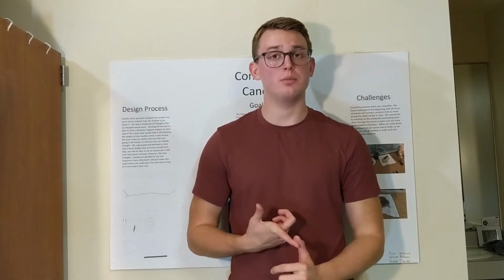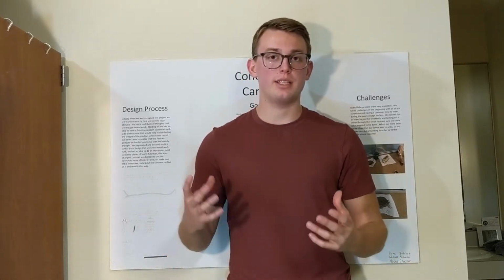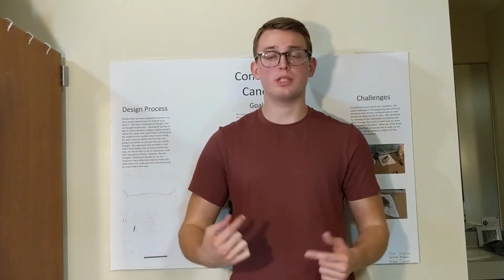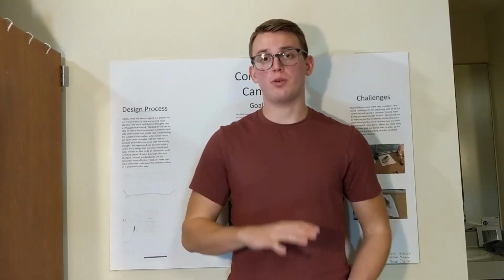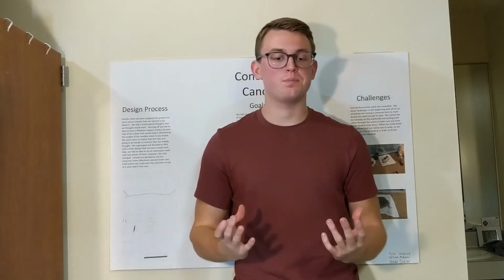So now I have to figure out what my concrete consistency needs to be to form a better mold. Now I also need to take water absorption into account and figure out how to reduce that, because concrete is naturally porous, and as the concrete absorbs water, it's increasing the weight of my canoe. And that increases my downward force, which makes the net force difference between the upward and downward force less. So it'll be less buoyant.